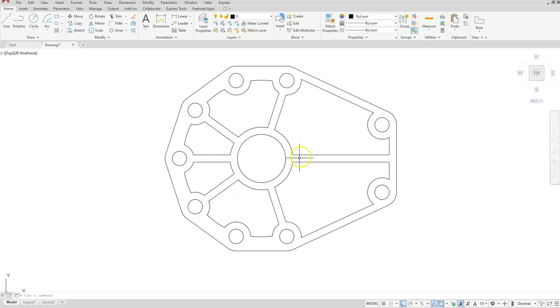Now one huge benefit of having these that way is that when I use the fillet command, I'll set my radius, which is 0.2, enter. I have multiple, and then I'll choose the polyline option. So I'll select polyline, select this polyline, then I have to come back and go to polyline, then I'll select this object, back to polyline, this object.